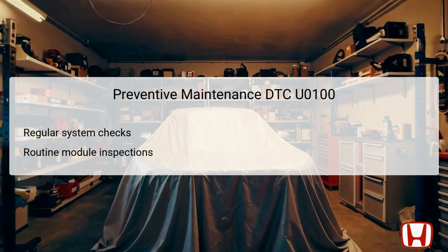Preventive maintenance for DTC U0100 focuses on the regular inspection of the vehicle's electronic control systems and communication networks. Performing periodic checks of the power and ground circuits related to the PCM can help identify potential issues before they escalate into more severe problems.